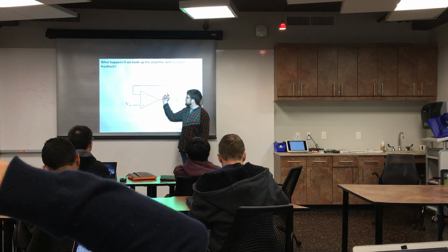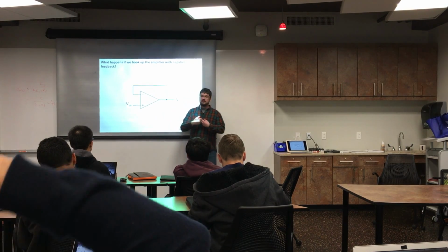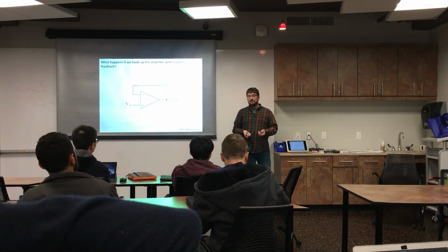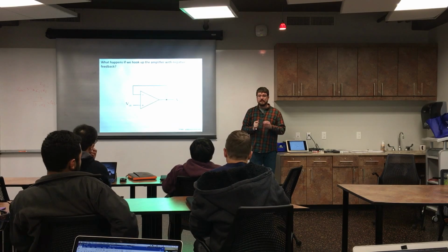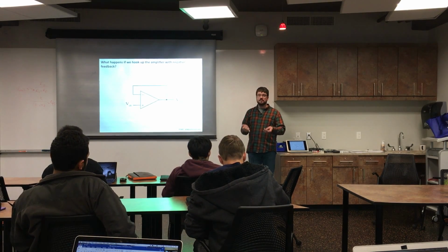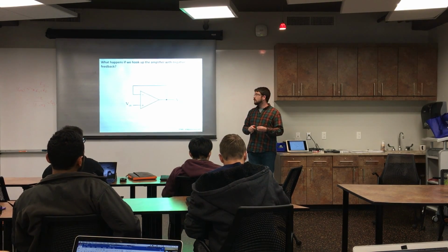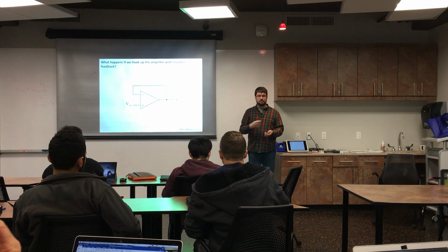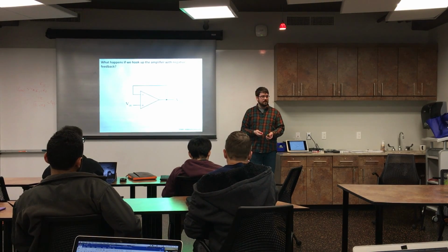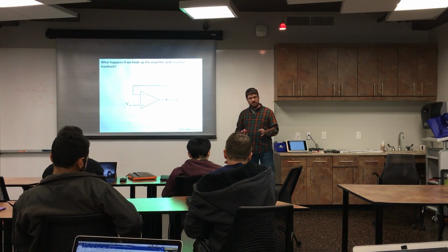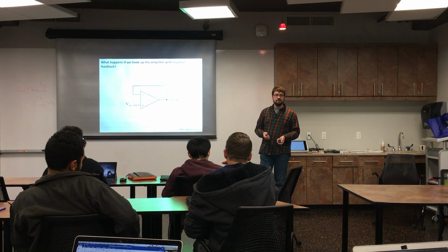I kept saying that this is increasing and it's feeding back and it starts backing off on its output. That does happen, but it happens in an incredibly short amount of time. This is all happening on silicon, it's all transistors. So you're looking at, for all purposes, an instantaneous response of the voltage follower. And when you get into really high frequency stuff, maybe that's not quite so true. And that's where you have to look at those plots in the data sheet.